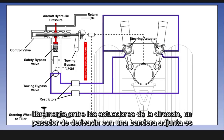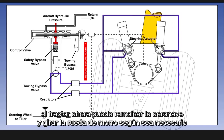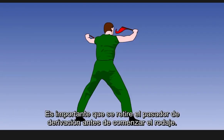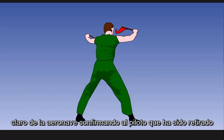A bypass pin, with a flag attached, is fitted to hold the lever in the valve open position. The tractor can now tow the aircraft and turn the nose wheel as necessary. It is important that the bypass pin is removed before you commence taxiing. It is normally held aloft by the dispatching ground engineer as he moves clear of the aircraft, confirming to the pilot that it has been removed.